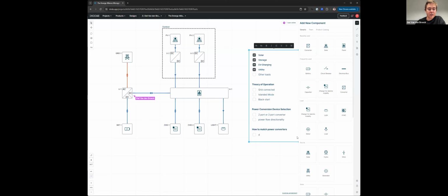The voltage at this port will be the voltage at this port, as we already explained. So obviously, the ranges should match. And in a DC microgrid, you have some freedom to select the suitable voltage level. 350 volts, 700 volts. That's where international standards are going today.